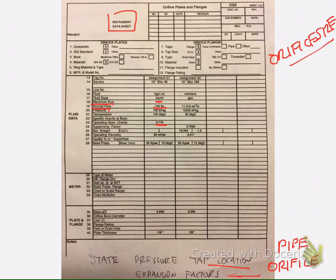And the other thing that we need to apply is, since it's the maximum flow rate that our calculator is asking for, and this is the normal, we're actually going to have to divide by 0.8 to figure out what our maximum flow rate is, because our program is going to multiply by that 0.8, so we need to divide it. But I'm going to key this in right now.